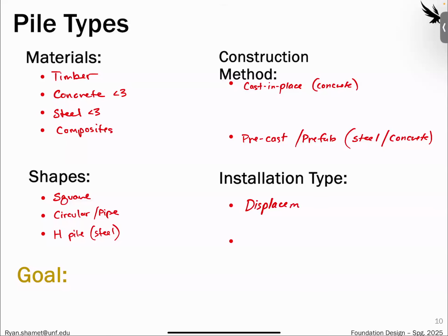meaning as we are installing the pile, it is displacing the soil or densifying the soil. The other word for this is a driven pile. So there's no pre-drilling of a hole or anything. We're just hammering or pounding a nail into the ground, essentially.